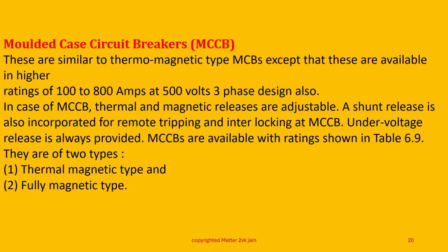In case of MCCB, thermal and magnetic relays are adjustable. In MCB, the adjustment is not possible. A shunt relay is also incorporated for remote tripping and interlocking of MCCB. Under voltage relay is always provided.